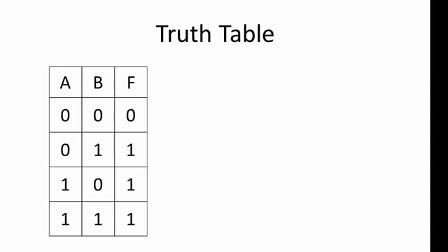So let's look at an example. Here's a simple truth table with 2 inputs, or shall we say 2 variables. You should recognize this as the truth table of an OR gate. Column F contains the output value for each combination of input values A and B. Strictly speaking, this is the truth table for any combination of logic gates that behave in the same way as an OR gate. So we could say that this is the truth table of an OR function. That's why we've called the output column F.